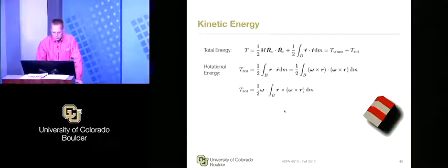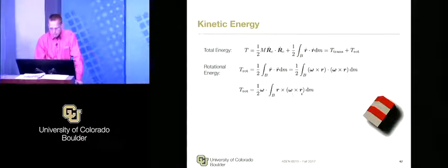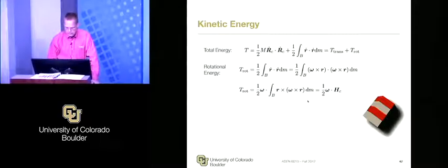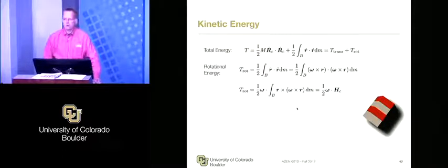So we use one here, to rearrange things, and this gives me this formula, where I have an omega outside. That's nice, because omega's outside the body integral. Every point on a rigid body has the same angular rates. This part, I get to reverse the order, which gives me minus R cross omega. And again, the omega I can take out on the right-hand side. And the stuff in the middle looks just like the inertia tensor.